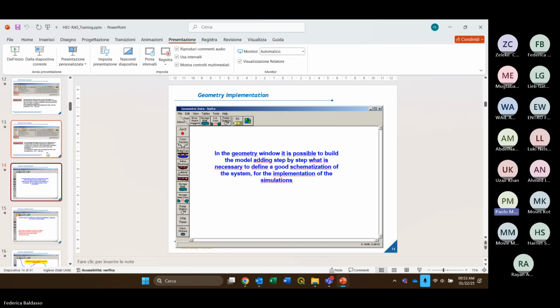That's just to say that yes, cross-section is probably the most important part of the geometry, and you need a topographic campaign to be completed before you start doing the model. If you don't have this data, you can use some ready off-the-shelf data that have significant limitations. So the results that you will get will be definitely less accurate. Okay, I hope this answers your question.